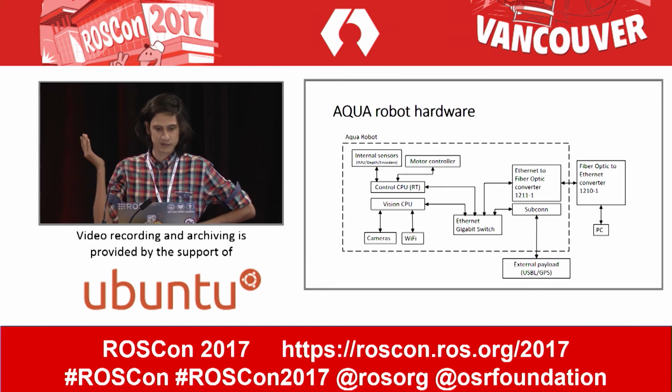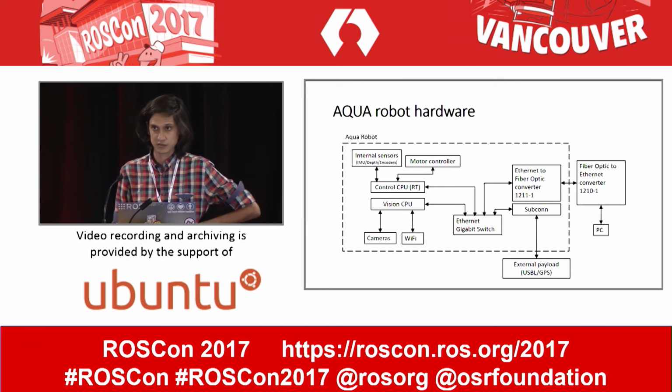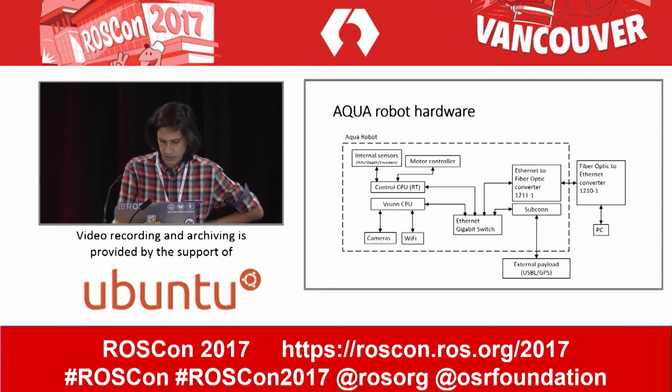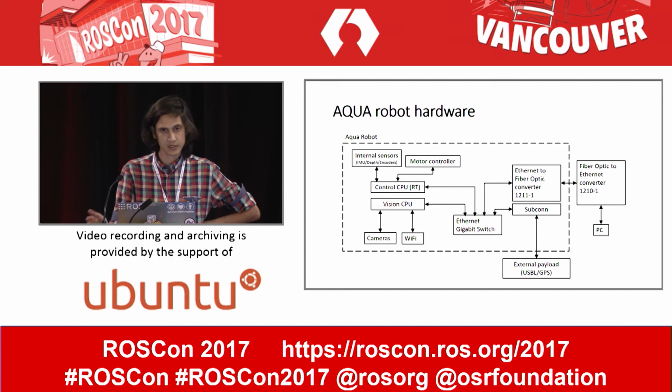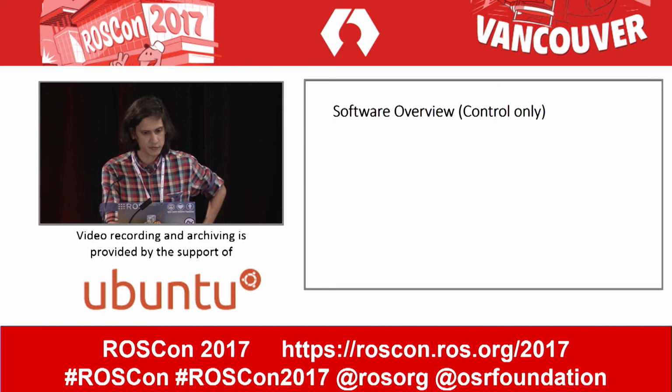The AQUA robot hardware is very similar to what you would find inside a drone. It's essentially a low-level computer that interacts with the motors, internal sensors, and power management; a high-level computer that we use for vision tasks and where we actually put all our ROS stack. All of it is connected through an Ethernet switch, which we can also connect to some external payload. For example, we connect it to acoustic devices for localization underwater. We also have a fiber optic to Ethernet link, which allows us to connect an external PC for monitoring or deploying other algorithms.